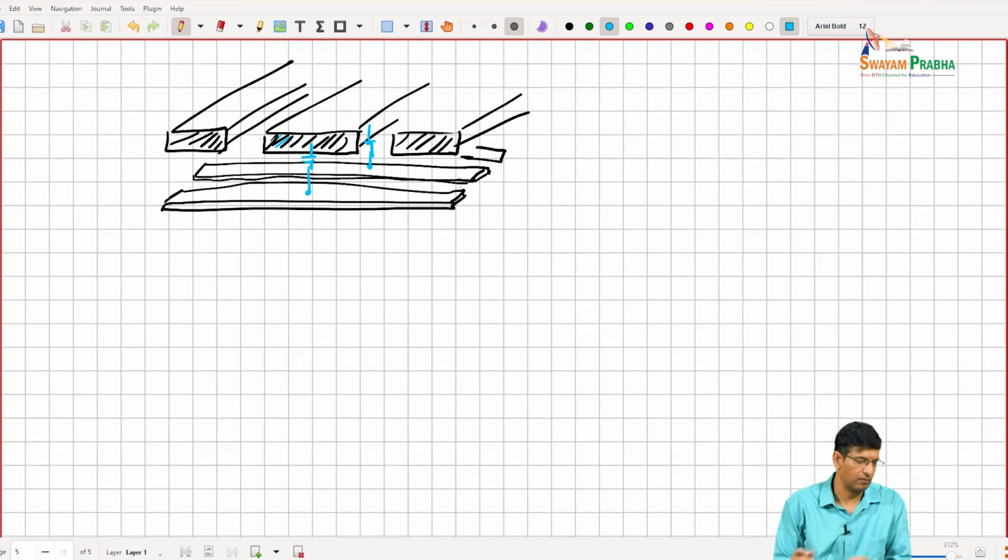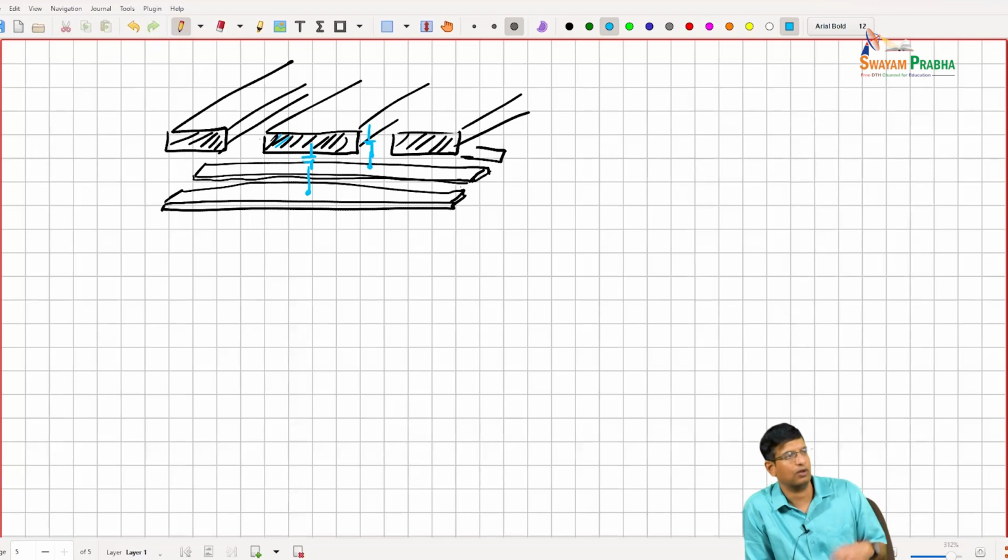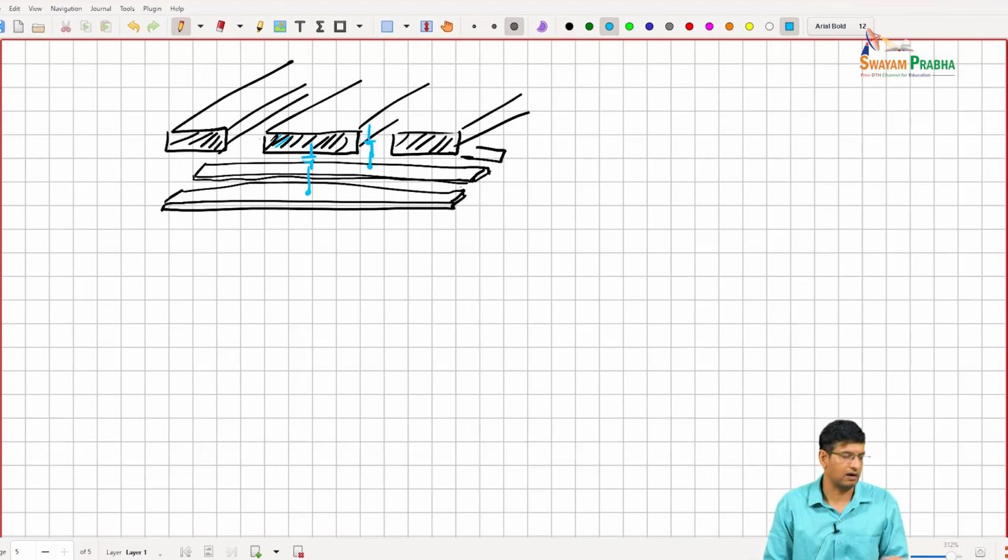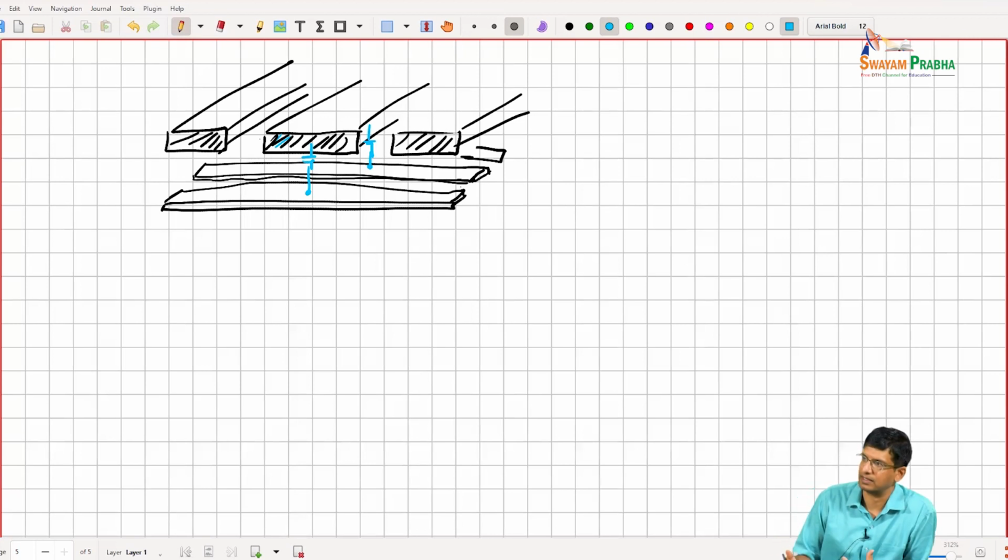With these kind of structures, the one issue does become that the impedance of this is low, right? Because we have loaded the transmission line. But it is worth noting that, like I said earlier, you are not constrained to a certain impedance on the chip when you're designing. And also many times when you are trying to get, for example, an inductance or a capacitance, the Z naught is also a parameter that is under my control, right?